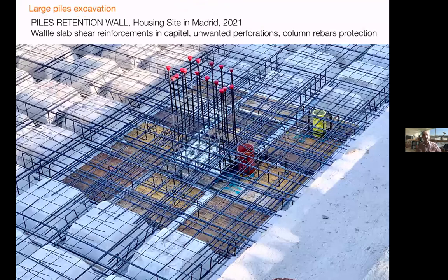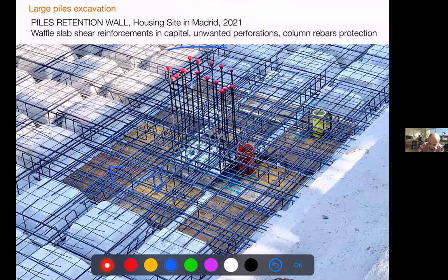And we are one minute over the time. So I brought this of the capital because we can see this kind of zigzag is this kind of shear reinforcement. And that happens again as soon as we have less concrete, we have to repeat again, right? This is vertical bars. And in this case, they did it in this way. Not so happy with these openings. You have to be always careful about them.